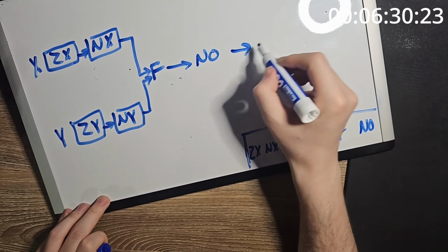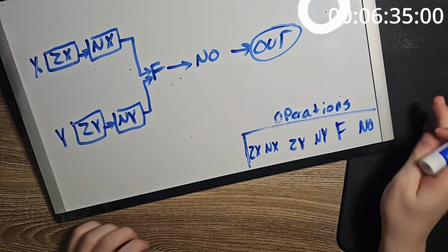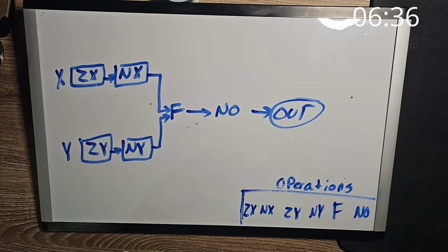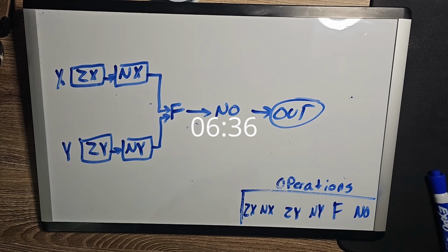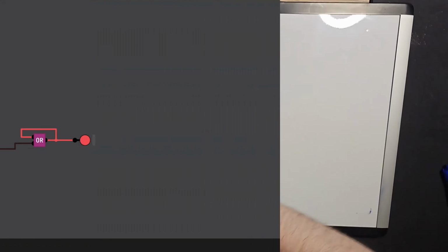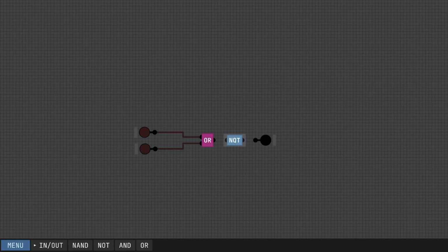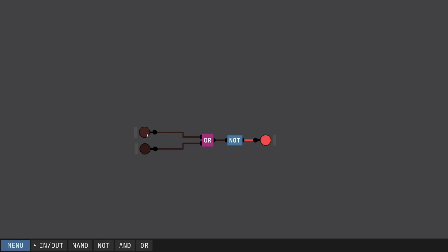We of course have many more operations than what I just listed, but that was pretty much the most important of them all. Whew, that took quite a second. Now that the ALU is complete, we can quickly recap registers. So it starts with this basic idea. I want to be able to hold a bit in a component, so that way when I come back to it, I can look at its data. It starts with a simple logic gate called the NOR gate. It is the OR gate, but its output is inverted.